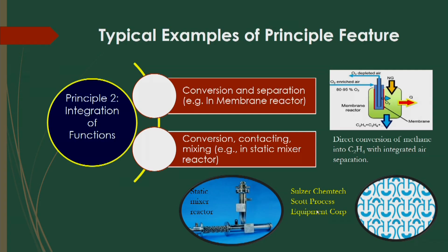That is obtained by estimating one important parameter called the Peclet number. If the Peclet number is going to infinity, that means there will be less mixing, whereas if the Peclet number is coming to 0, then it is called higher mixing or complete mixing. So, you have to intensify the unit to increase the process intensification phenomena based on this integration of functions.